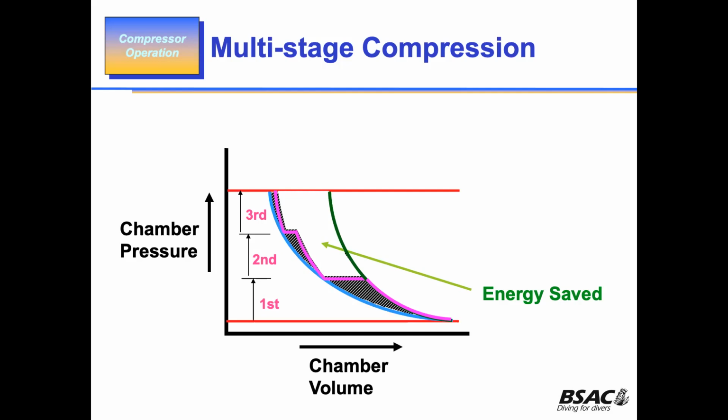But in some very, very high pressure compressors, you may find 4, 5 stages of compression. And the bore of the final stage is quite small, but the pressure coming out of there is quite high. So that is basically what we're looking at with the diving compressor.